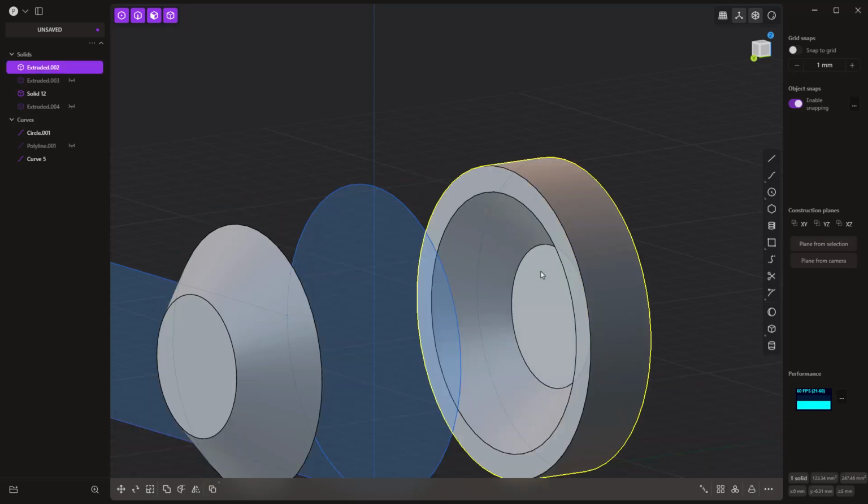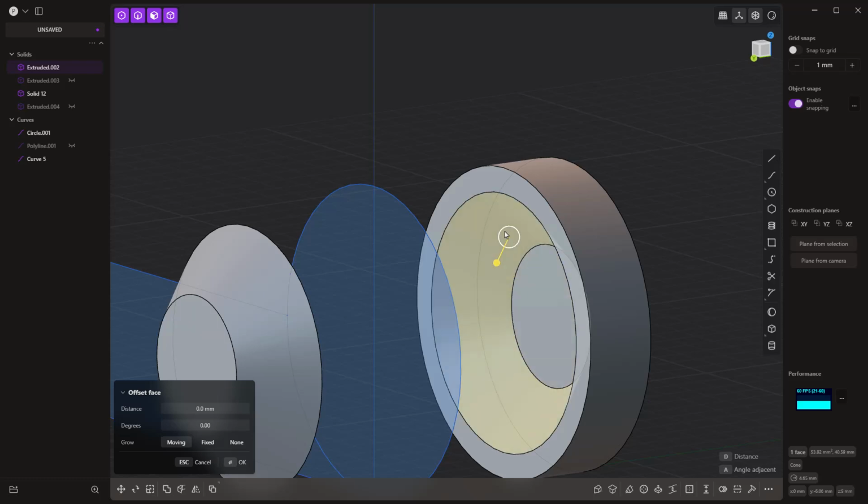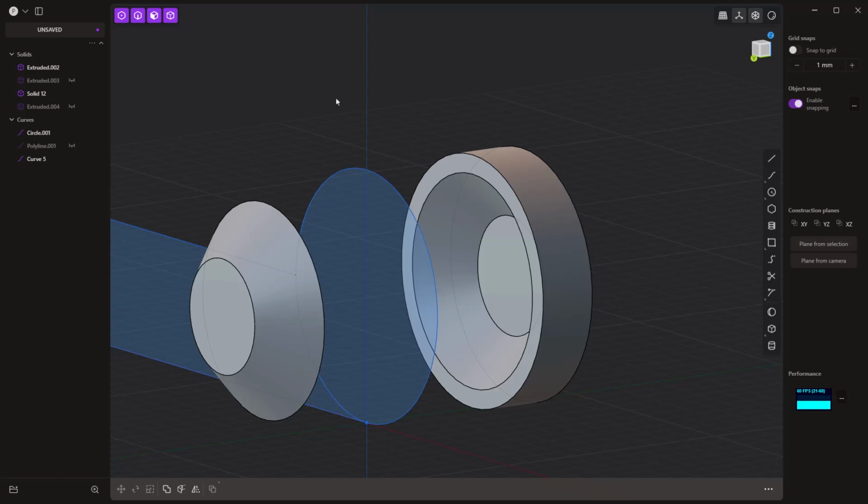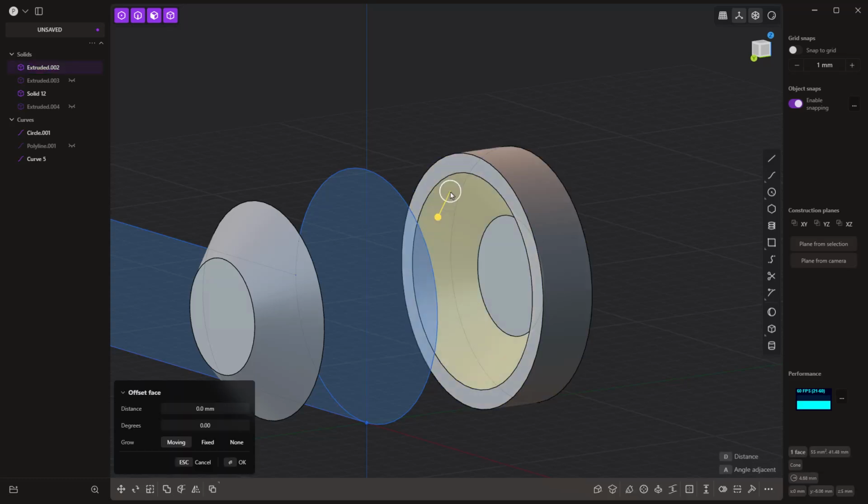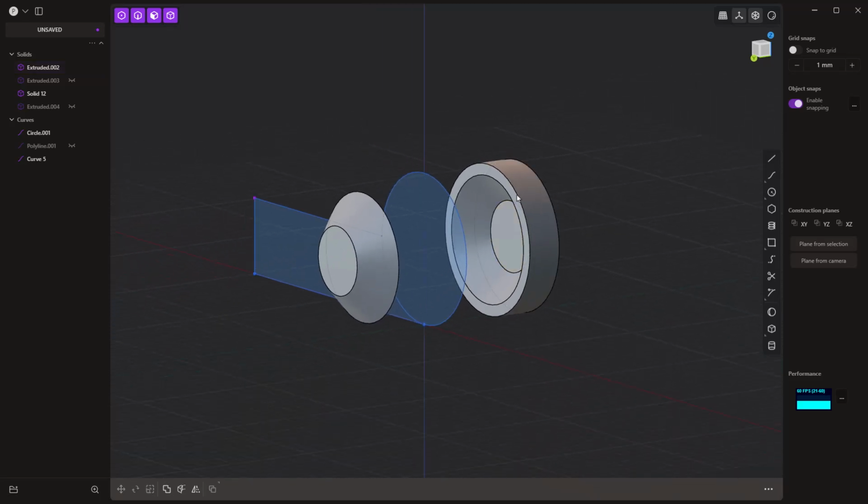But right now, this face and this face are perfectly matching. I'm going to leave the outside face exactly matching the location. And again, because we're printing these separately, we can do that. And that's a good way to control how tight the tolerance is, or how tight the joint is itself, and how well it stabilizes. But we can't have this piece be exactly the same. So I'm going to add a small gap, but not as big as that 0.125. So we're going to do minus 0.05. And what this does is it gives us a small gap between the pieces. We have a small gap between this face, a small gap between this face, and exactly matching with this one. So that's how we're going to get a nice tight joint.